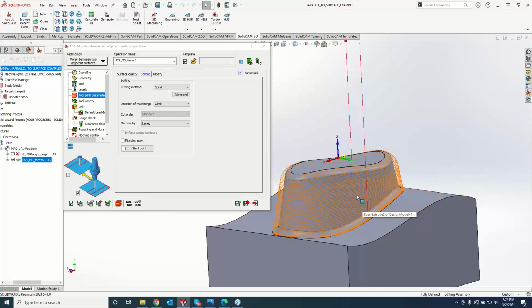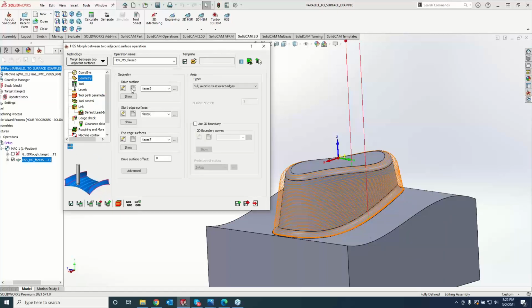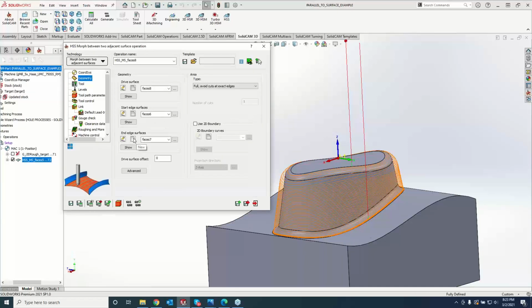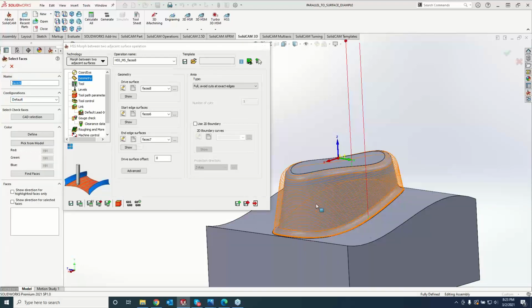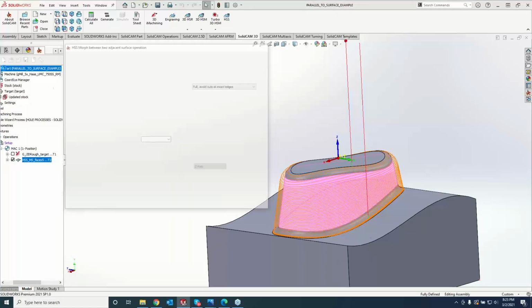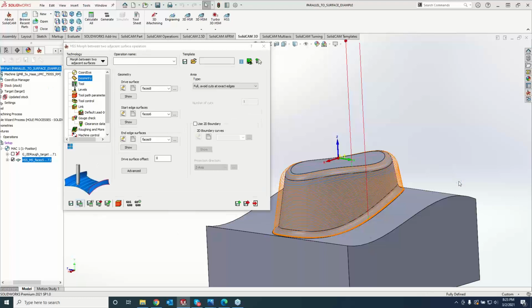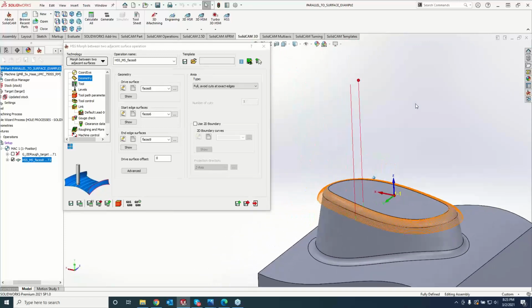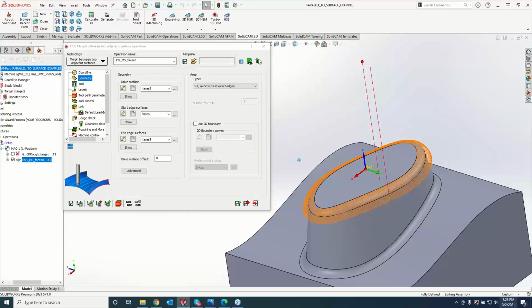And of course, maybe where I see this being used the most is just doing the radiuses. So if we come over and we'll just tell it that it's that radius right there, our start curve is still going to be the same, but we want it to end right here. This works wonderful for doing these 3D fillets. So you can see you've got a nice toolpath working its way all the way around the outside of the part. One starting point, one finishing point.